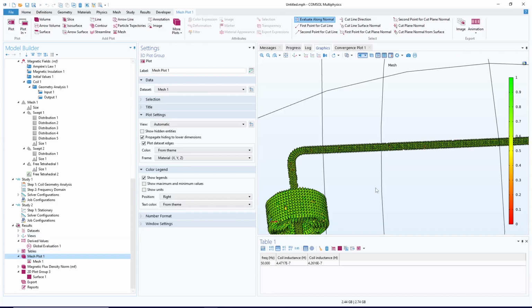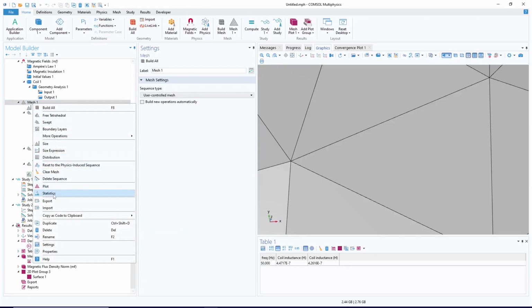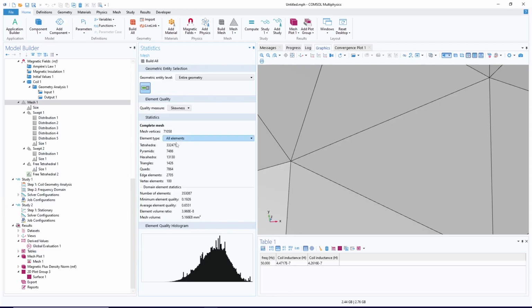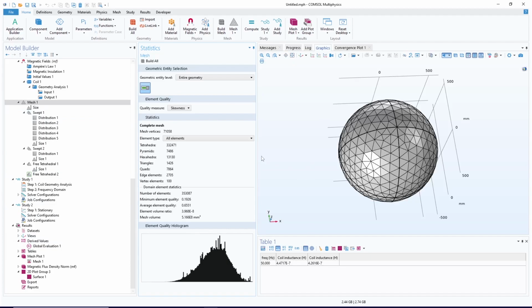Okay, so if we look at this, you notice that this is very good. And the statistic again, this one is also really good. Mesh 330,000. The number of mesh, as I said, is very important. For example, my computer has 32 gigabytes of RAM. I don't want to go more than a million or maybe 1.2 million mesh. Then it becomes very slow. So depending on the size of the RAM that you have, you should really control how many mesh you create. Otherwise, your simulation will be extremely slow. All right, so we have created this.